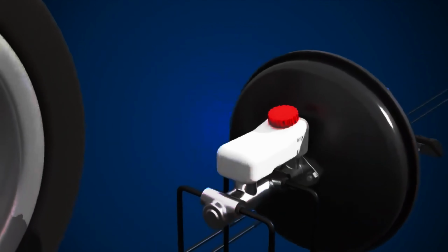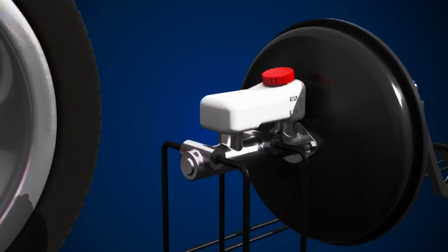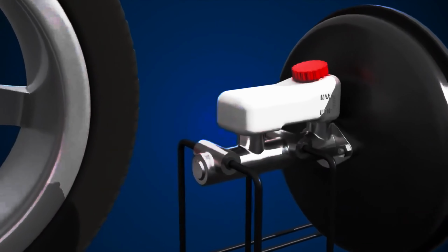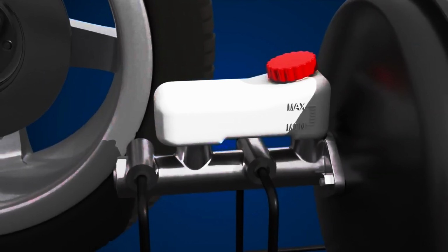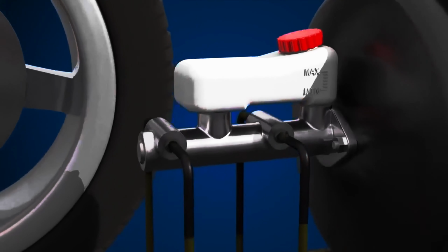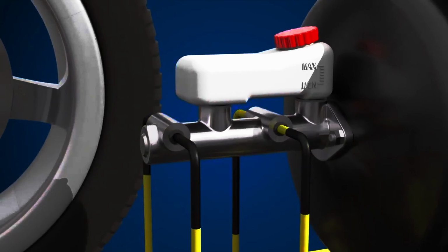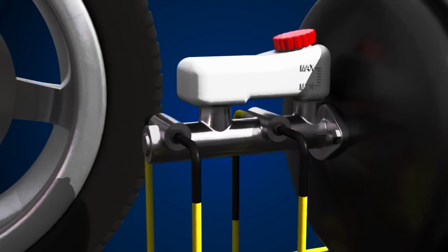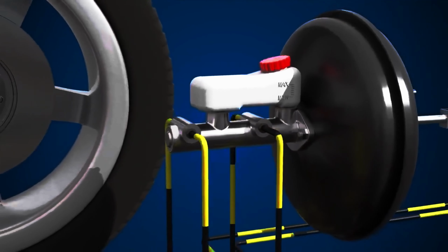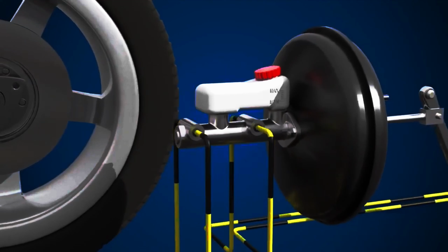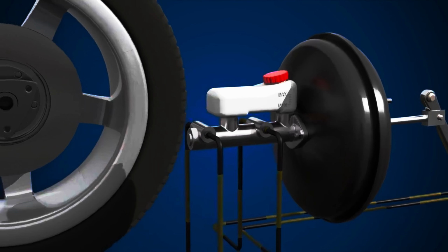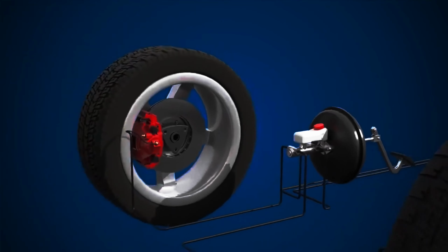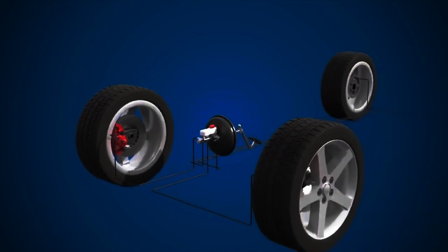The master cylinder converts non-hydraulic pressure from the driver's foot on the brake pedal into hydraulic pressure. When braking, pistons with seals and springs in the master cylinder create hydraulic force, which pressurizes the entire hydraulic system. Brake fluid returns to the master cylinder when pressure is released. The reservoir holds sufficient brake fluid to stop air getting into the hydraulic system. Finally, we have the hydraulic lines, which carry the brake fluid to the front and rear brakes.